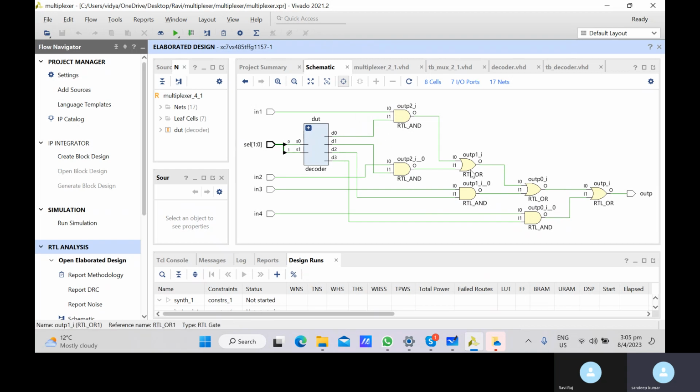In one is 0, and then an OR gate. It has created a chained OR because it selected a 2-to-1 OR gate, as in libraries usually 2-input OR gates will be there. So it selected one for each, chained OR basically. It's ORing this, and ORing this output, and ORing this output, so together and then the output.